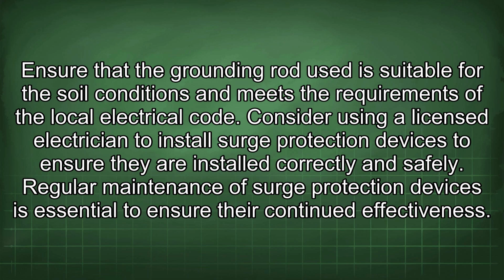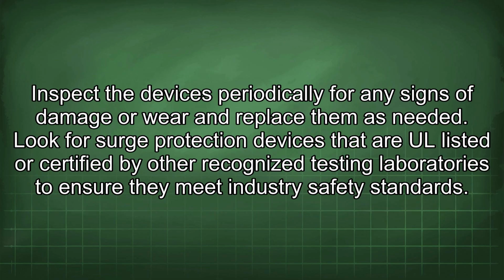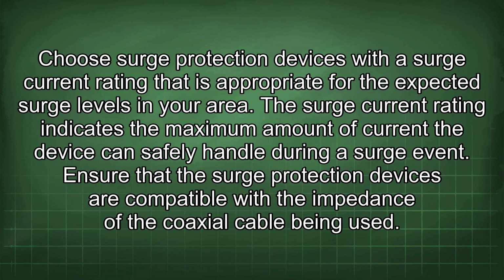Regular maintenance of surge protection devices is essential to ensure their continued effectiveness. Inspect the devices periodically for any signs of damage or wear and replace them as needed. Look for surge protection devices that are UL listed or certified by other recognized testing laboratories to ensure they meet industry safety standards. Choose surge protection devices with a surge current rating that is appropriate for the expected surge levels in your area. The surge current rating indicates the maximum amount of current the device can safely handle during a